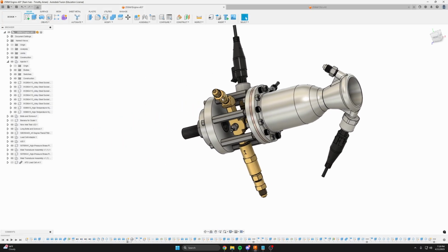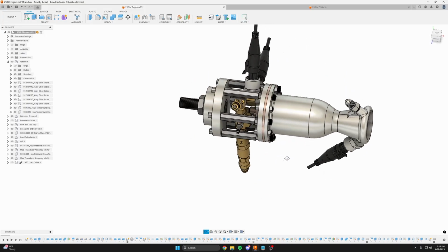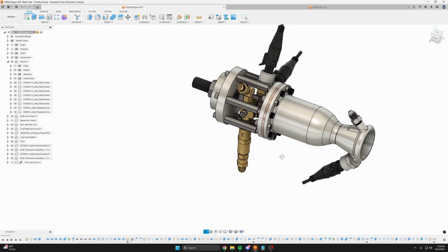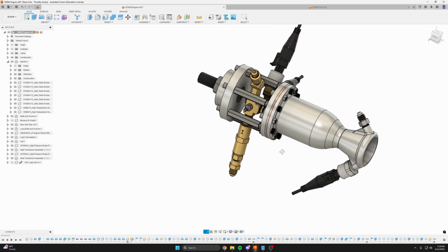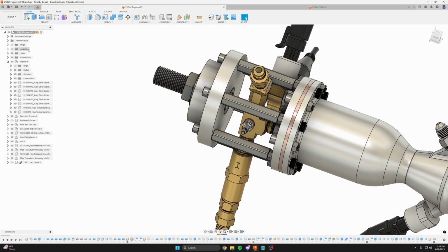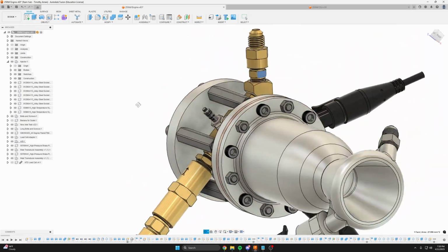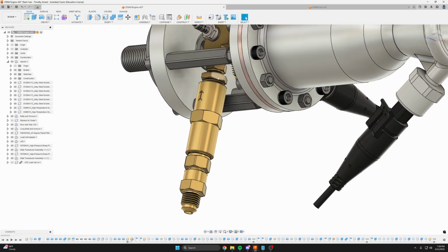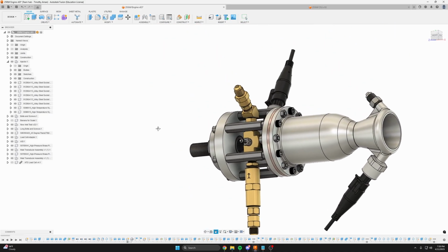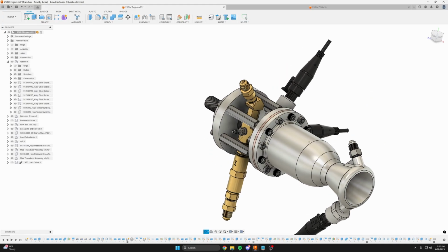I will say, for an augmented spark igniter, it is much easier to achieve combustion in the ASI with just the spark plug if one or both propellants are gases. Ideally, both would be gases, because in this case you're not using any sophisticated injection technique. There's just a simple orifice that sets the mass flow rate for both, like a simple orifice fitting, I think here and somewhere downstream here.